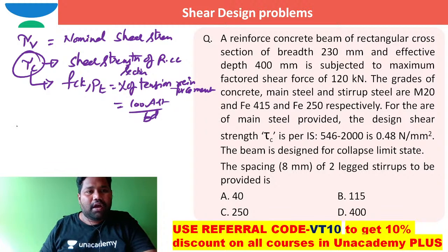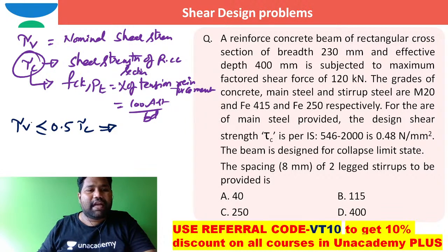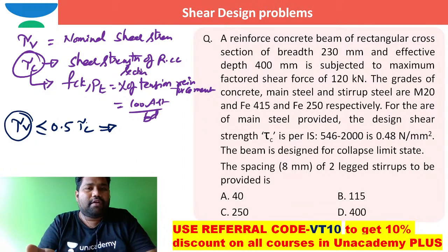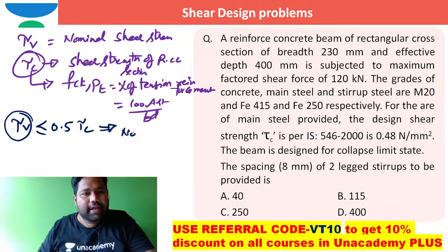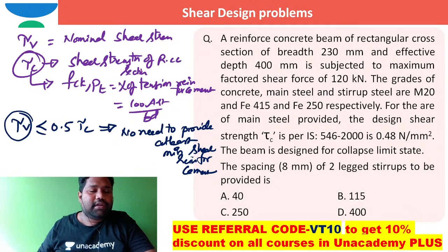The clause is: when tau v is less than or equal to 0.5 times tau c, in such a case there is no need for even minimum shear reinforcement. That means the developed stress is 50 percent less than the shear strength of the RCC section. In such a case, there is no need to provide minimum shear reinforcement.